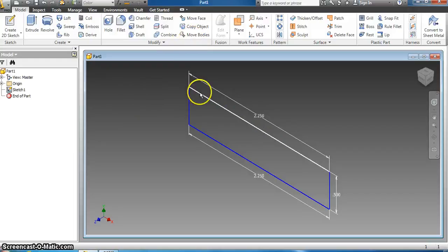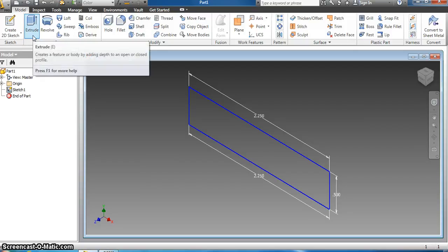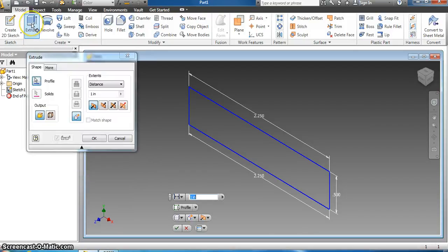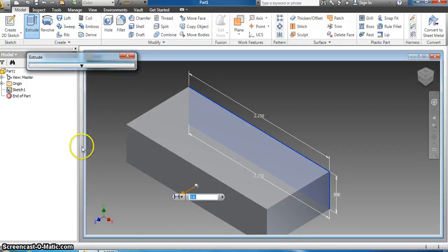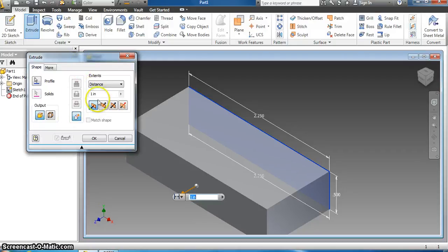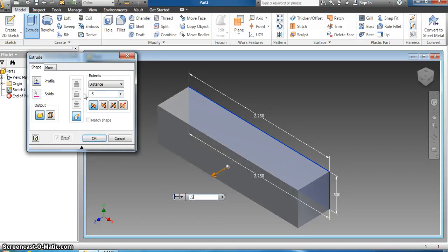We see we moved from the sketch window to what's known as the modeling tab. What we're going to do is extrude this, giving it a three-dimensional look. If you click on extrude, currently we only have one surface that we can extrude. If that window is ever hidden, you can click the drop down once you click extrude. The default is typically 1 inch if you're working with inches. Let's say we wanted to extrude at 0.5. It'll show us a preview.